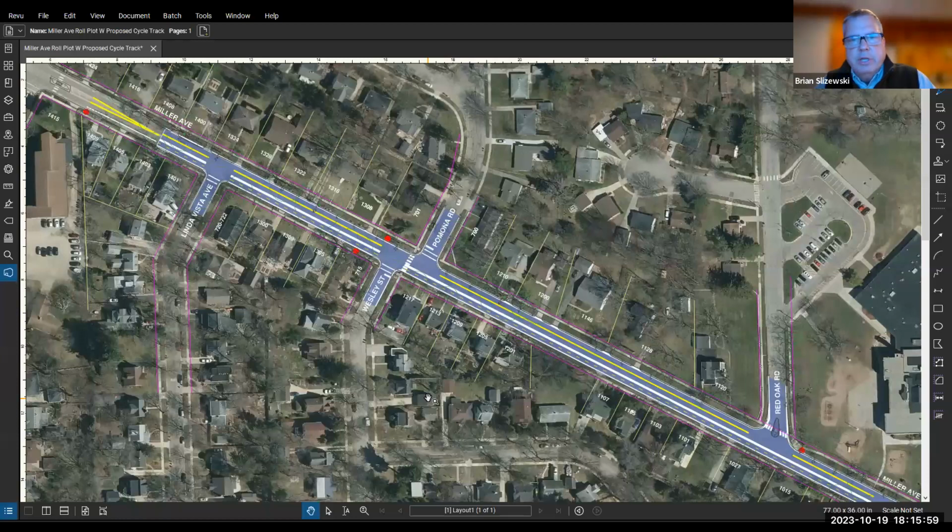There are challenges. Everybody coming into town is aware you are cruising downhill there, going from west to east. There are sight distance challenges. Traffic is certainly speeding up as they're coming into town, going downhill. So we need to look at speed management and sight distance.